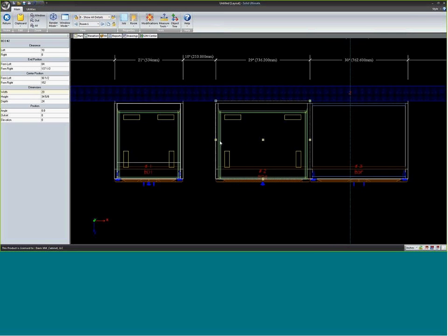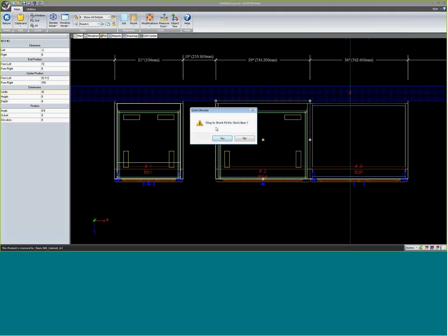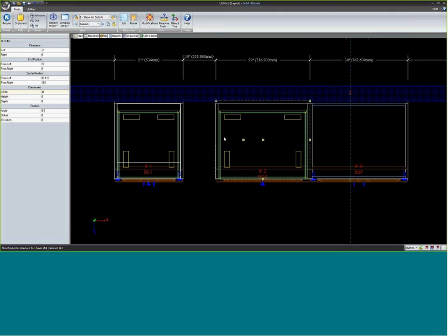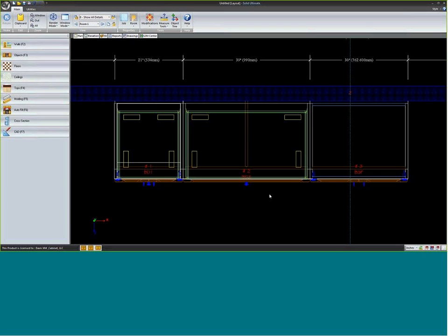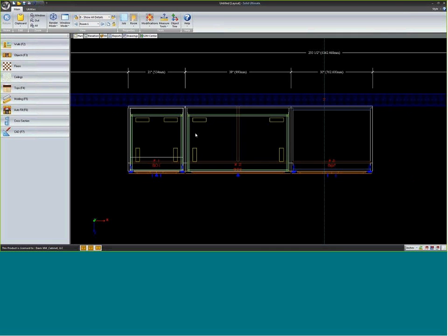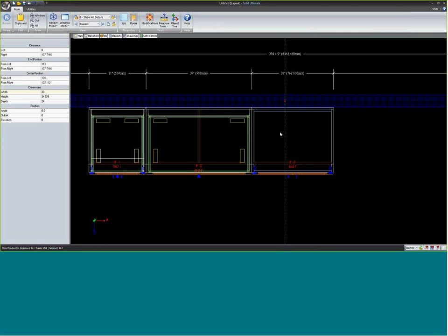So it'll snap to, and it can do it over here and snap, just overlap slightly. And this time asked me, do I want to shrink fit this item? Yes, let's do. So there it fits the gap. And I'm exactly 39 inches between those two cabinets. So that's the ways to resize a cabinet, either the bar parameters or dragging these handles.